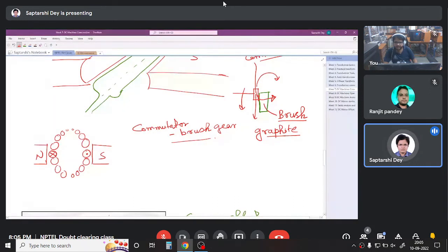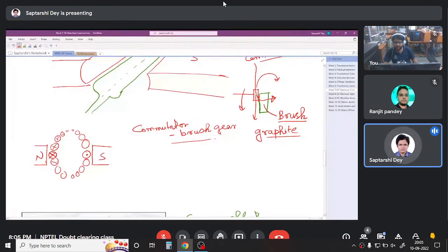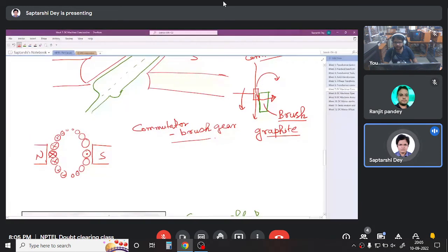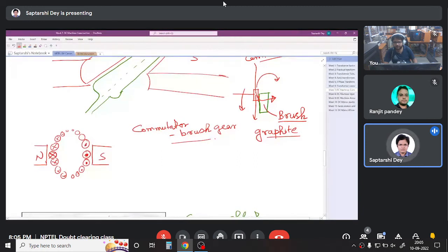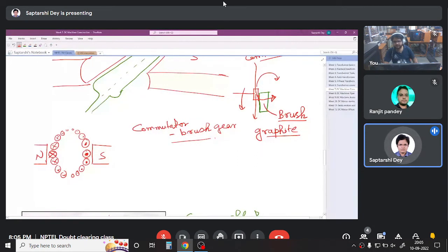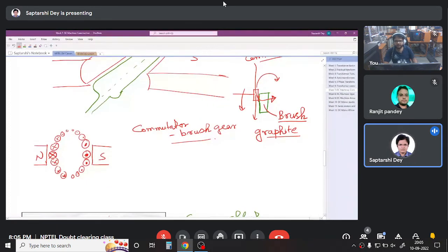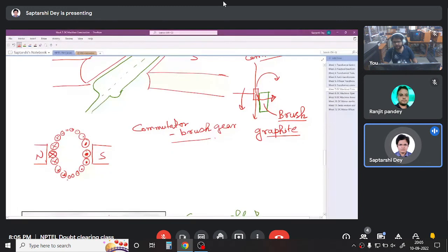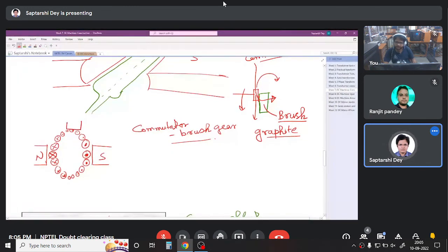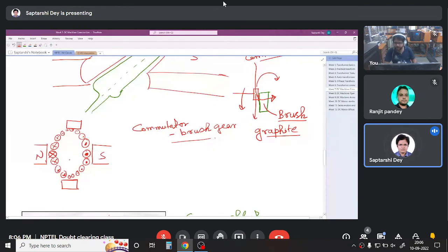So I have a large current, the maximum current here, it is reducing, no current. Again reducing, no current. Again, no current, more, very large current. Again reducing. So this is the current distribution that we have inside the armature of a DC machine. And the conductors present here are not carrying any current. Now, obviously the brushes are not touching the conductors, but for the time being, let us say I have a brush here,